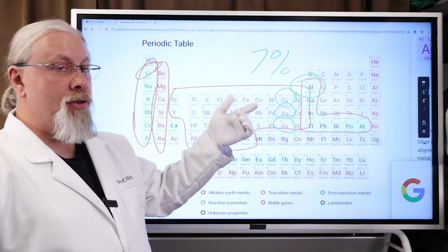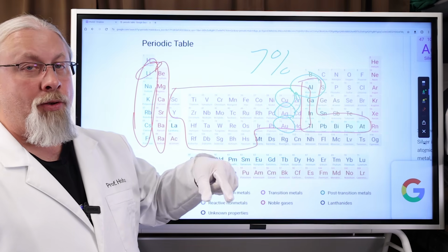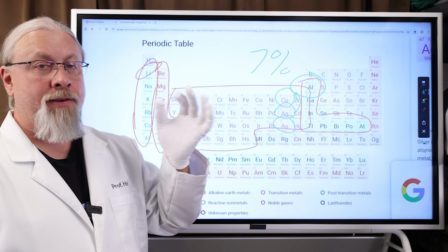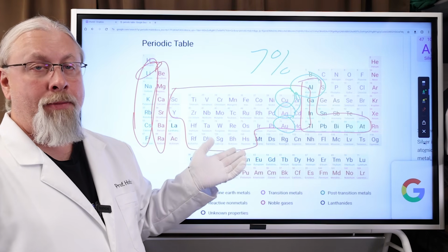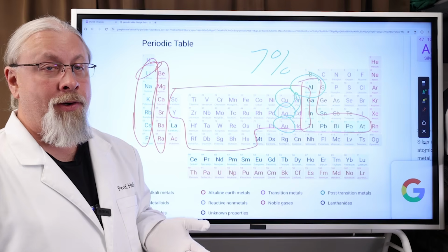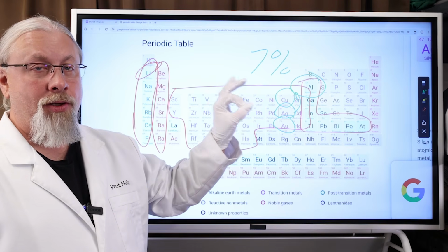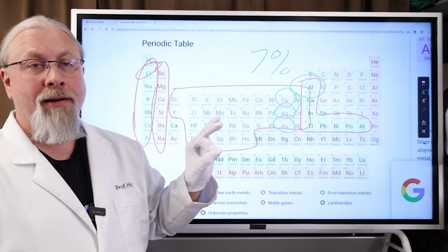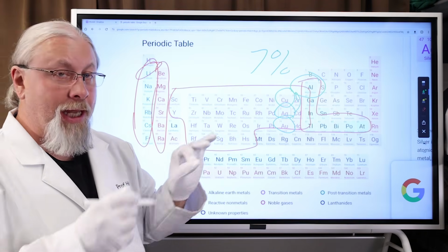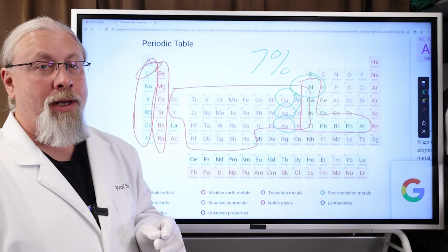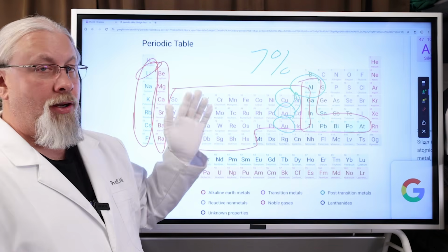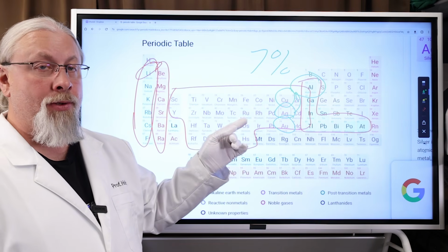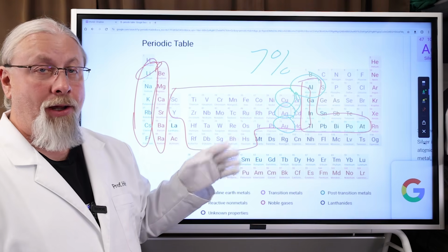Now, one of the major issues with using aluminum, especially in a solar build or in your home wiring, is that the cables need to be virtually double the thickness to transfer the same amount of amps, and that can be problematic because a lot of solar charge controllers and some inverters only have connector lugs of a certain size, and those are designed for copper. If you try to stick an aluminum cable in there, it's just not going to fit, because the cable would have to be almost twice the size to transfer the same amps. Also, aluminum has a much lower melting point than copper, meaning if your aluminum cables overheat, they have a much better chance to melt and cause a fire.